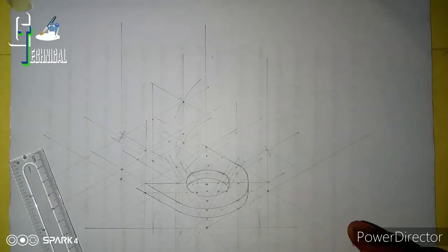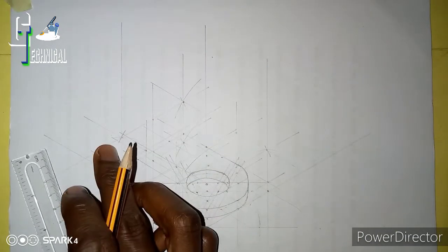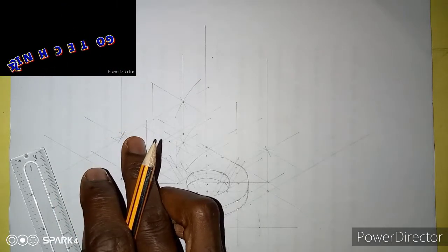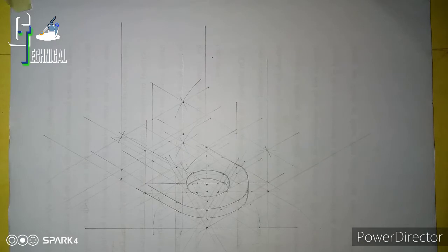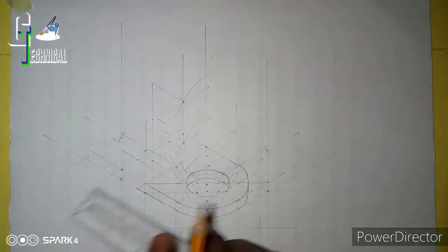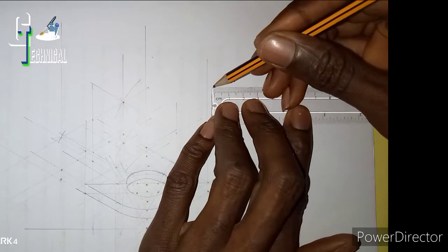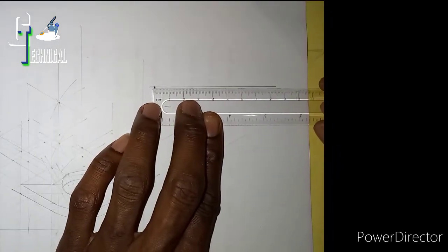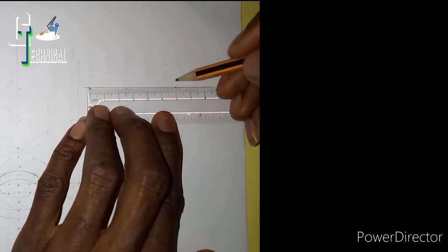So now, to convert the angle of 30 degrees, that angle of 30 degrees which it has been projected to, convert it now, what you have to do is to project a line converting that 90 degrees to 60 degrees. So what you have to do is to draw a line. Now you take a point. Now divide that line into 6 parts, which is 60 degrees. Okay, from 0 to 60 degrees.